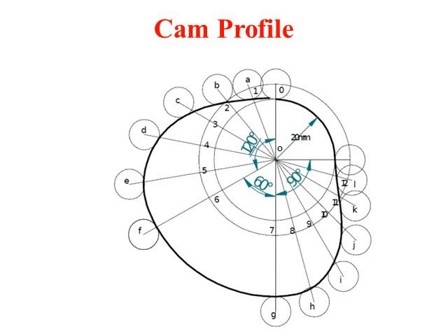Same way, measure 2B from the displacement diagram, come back to the cam profile, and with 2 as the center, remember this 2 lies on the prime circle, cut an arc. Mark it as B. Same way, we have to mark all the points.